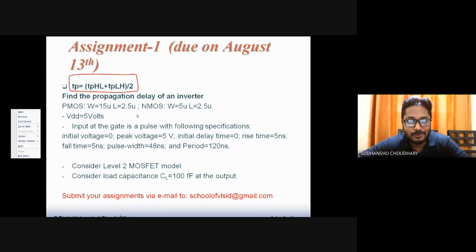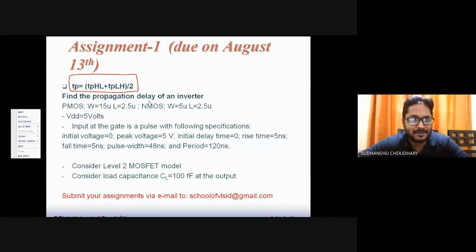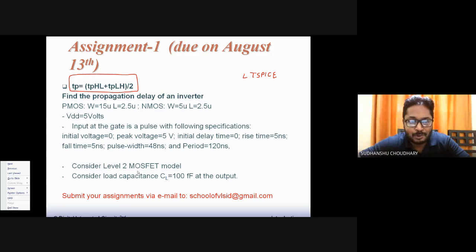Once you do the SPICE simulation, I don't know which software you use. Which software in the lab did you use? I hope PSpice or CAD? LT-SPICE. Yes, LT-SPICE is also good enough. Any software you can use, but since you have started using LT-SPICE, it is okay. In LT-SPICE, you can also edit the model libraries, that is, MOSFET models also. There are many tutorials available on the web on LT-SPICE, which you can go through.